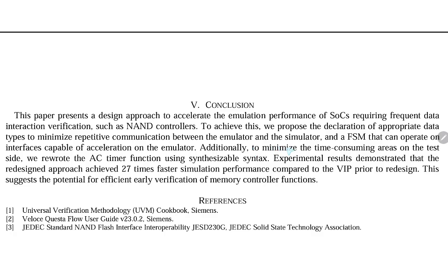Additionally, to minimize the time-consuming areas on the test side, we rewrote the AC-timer functions using synthesizable syntax. The experimental result demonstrated that the redesigned approach achieved 25 times faster simulation performance compared to the VIP prior to redesign. This suggests the potential for efficient early verification of the memory controller functions.